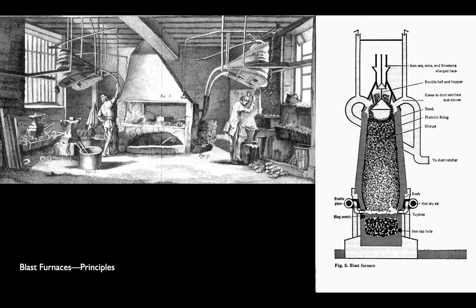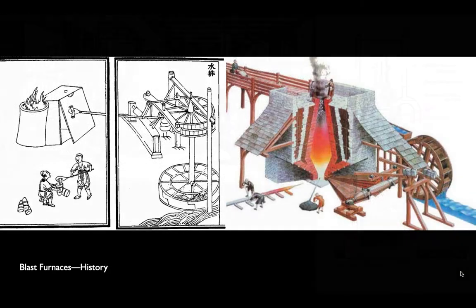On top of the molten iron is a layer that's called slag, which is mostly impurities. And then what goes on top of that ends up being the ash from the coal that burns. So it's taking advantage of the fact that all of these things act basically as a fluid once they get hot enough. And iron being heaviest, it sinks to the bottom where you can tap it off and get raw molten iron or pig iron.